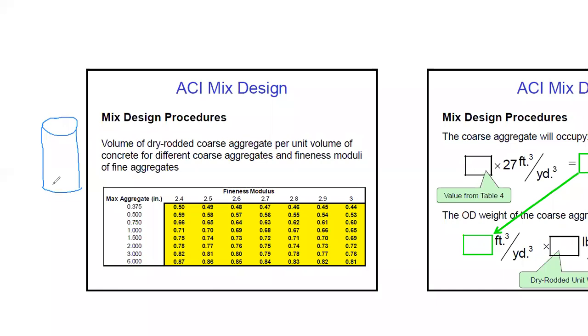If it is only filled by the coarse aggregate and there is nothing to go into the gaps between those coarse aggregates, what would happen? The coarse aggregates would come in contact with each other, and we are rodding these coarse aggregates to fill in the gaps appropriately, like they are being compacted by the rodding method. Okay? But there are some open voids and holes within this space, like the spaces in there. These spaces are obviously going to be there.